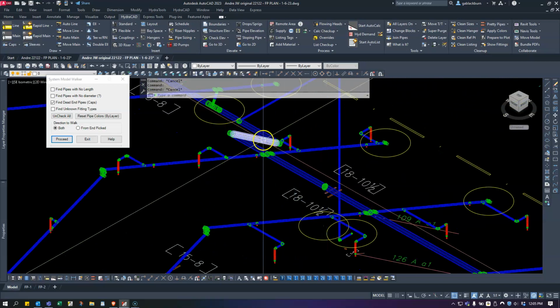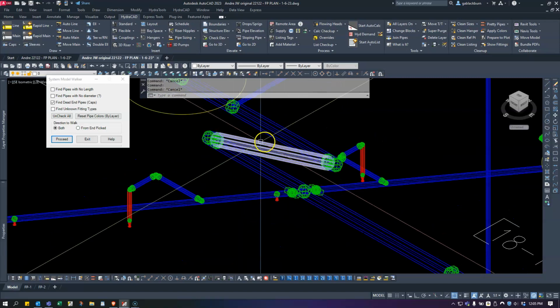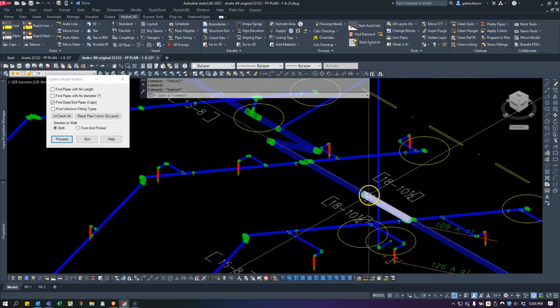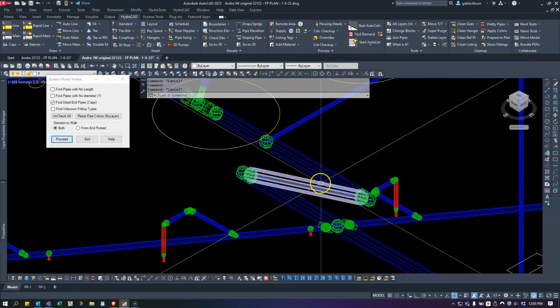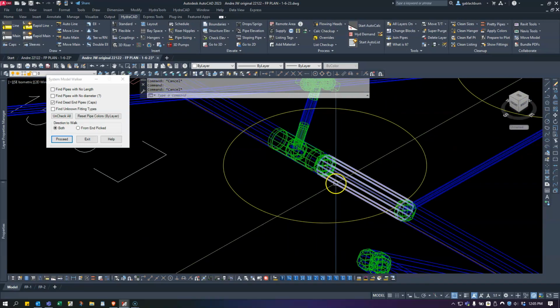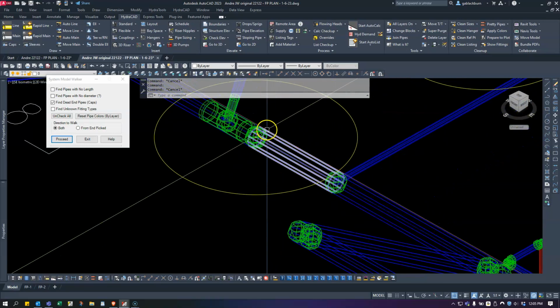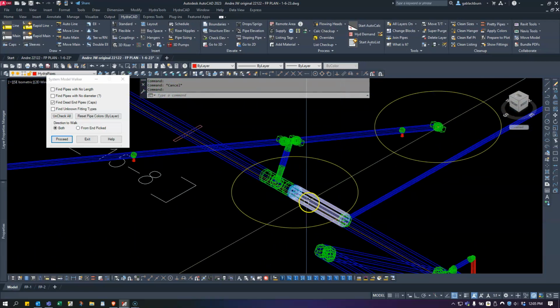Now, like I had said, this end user forced the slope right here. And what they're doing is they're telling it, okay, no problem, go 18 foot 10. We're going to pitch it at the pitch that you told me to pitch it at. We're going to run across, and as soon as we have a break in the pipe, like a coupling, I'm going to readjust my value. And that's what's happening right at this coupling right here. And when we go back down to 2D, we'll see that happening.